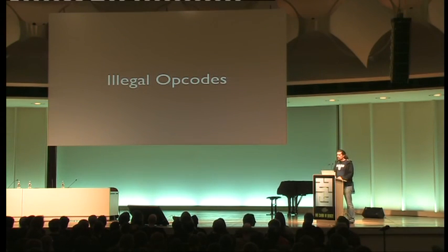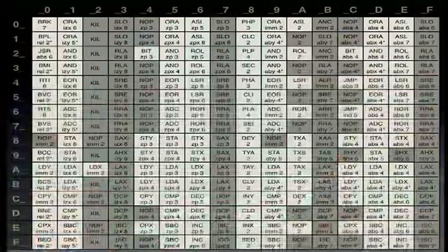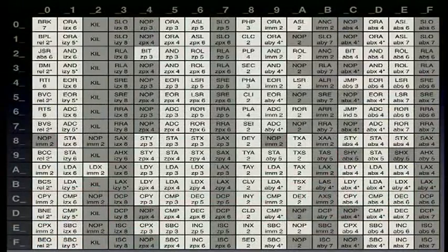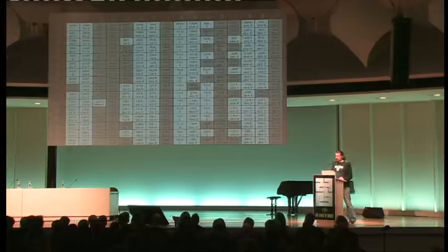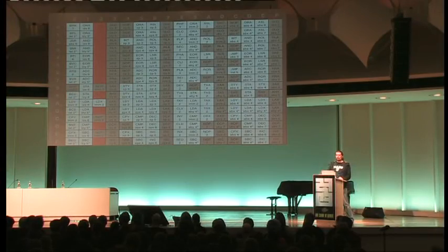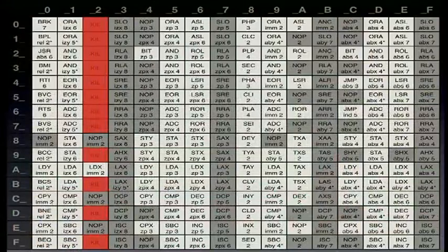So now this is illegal opcodes. These are the holy grail of all understanding the 6502, and I think we have made some progress there. What people have done so far is mostly, well, measure them and see what they are doing. And there were some theories that they seem to combine the ones that are close to them, but now we can say a lot more about them. So the kill opcodes, for example, most of them that end in 2, they just halt the machine. Reset still works, but IRQs and NMIs won't get delivered.